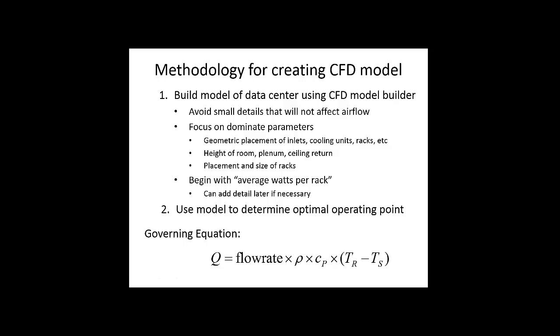So what we're going to do here is create a CFD model of a data center. And by the way, when you're building these models, my recommendation is to avoid the little stuff, the small details that don't affect airflow. Whenever you're doing modeling, we have to focus on the dominant parameters.